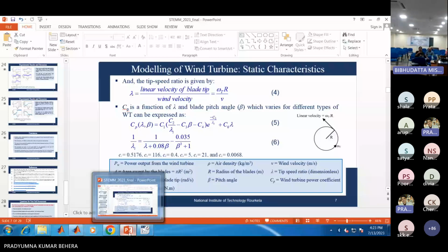See, suppose we are controlling a DC to DC converter, and I want to regulate the output voltage of that converter. Suppose I want to regulate it at 100 volts. I will take a reference of 100 volts, sense that voltage, compare it with a comparator, and the output will be processed through a PI controller first. Then it will generate a current.